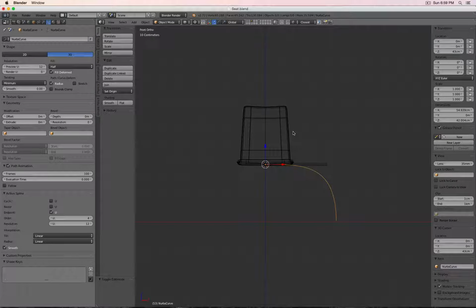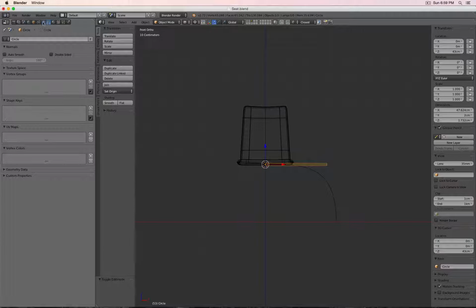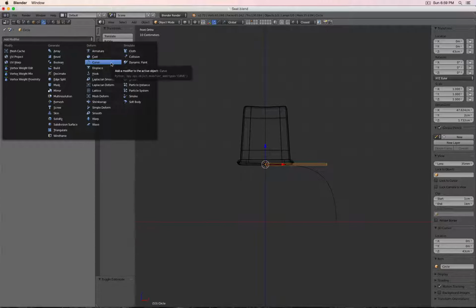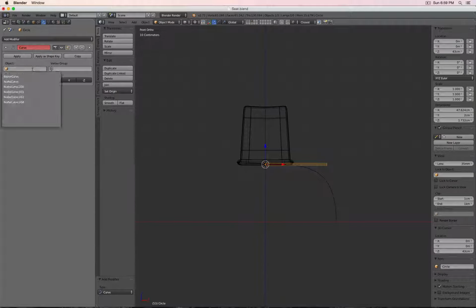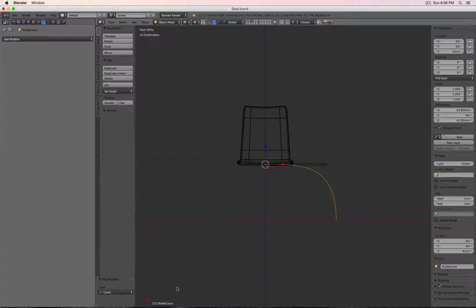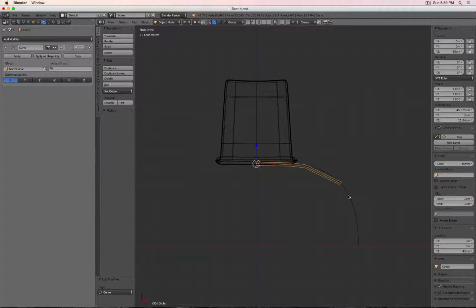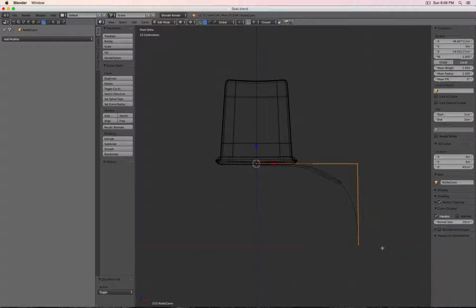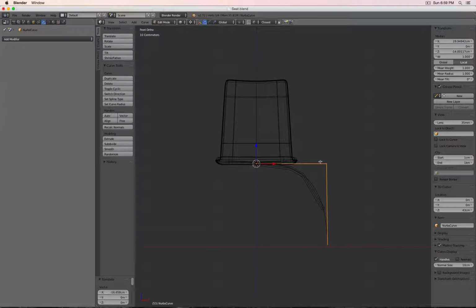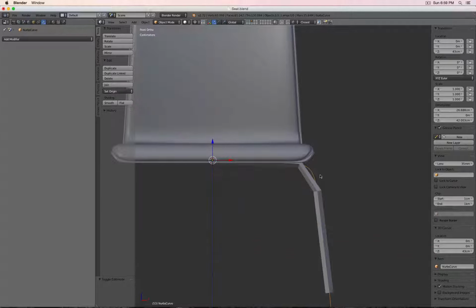So you see I can use a spline for the shell, or a NURBS curve, and then here now I go ahead and say deform. So I take my straight pipe, and which one is it? NURBS curve. There, bend it along it. Okay, obviously the proportions aren't right. So let's move this one inwards to there and there, and maybe here in between. Let's subdivide it with W, move maybe these points a little bit closer together, and let's take a look.